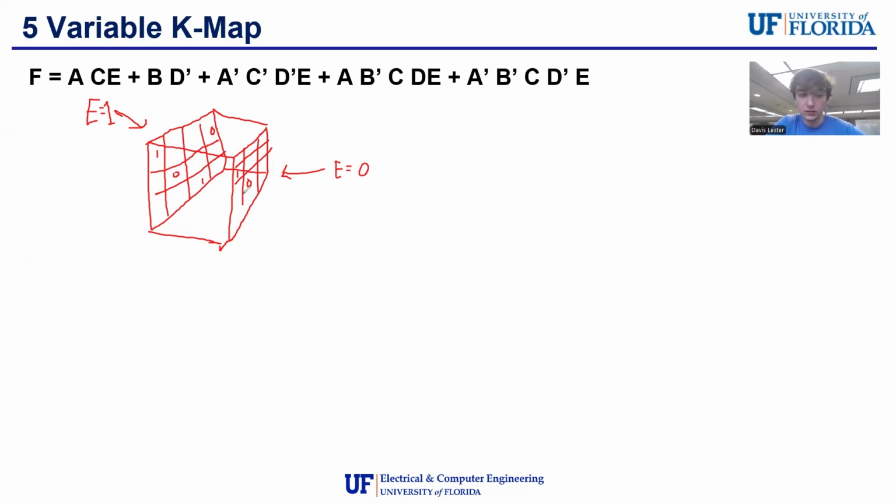But I just did E for this example. So in this way, we can have E equals 0 and E equals 1. We can circle across or through the K-map. Because remember how K-maps work is you're circling across things so that you can reduce the amount of variables. If I have something that's true, let's say this 0 was a 1.